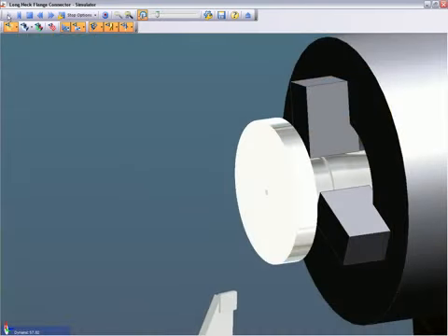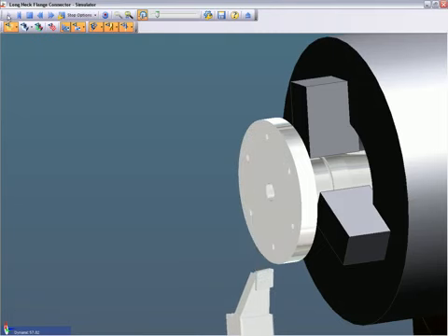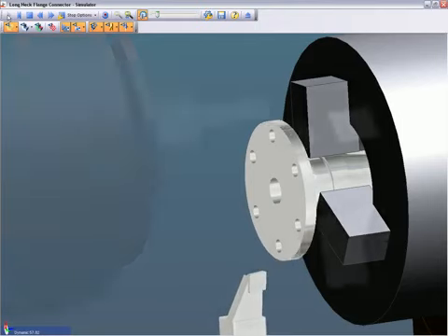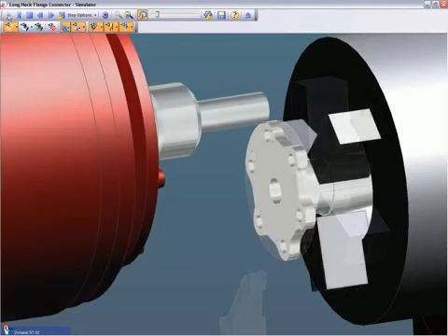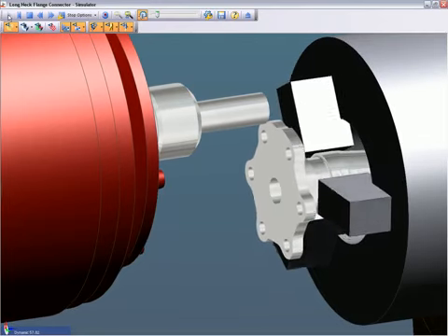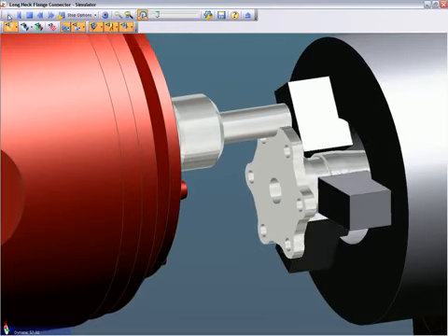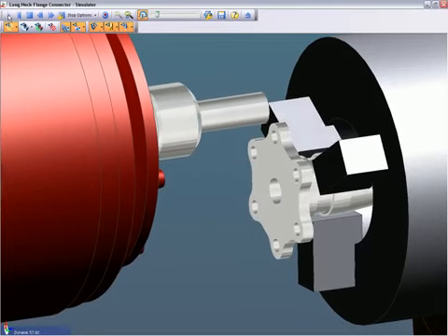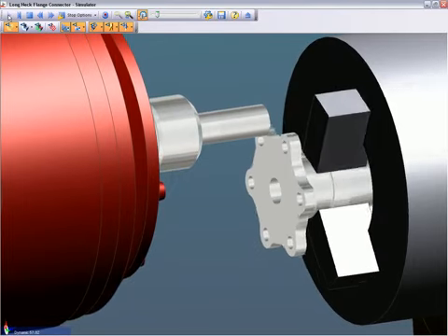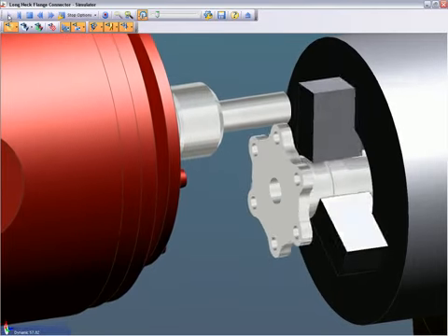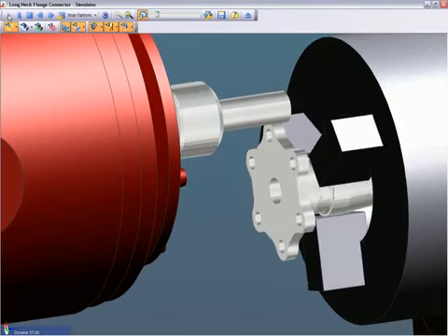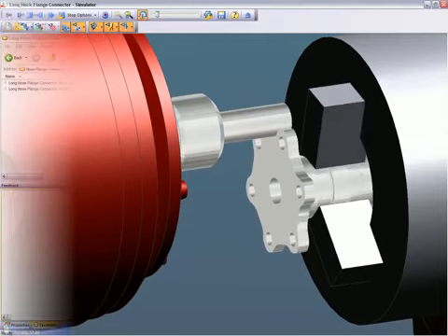Strategy Manager works on the information from the design intent of the 3D solid model. The solid model features have detailed information which will drive tool selection, approach values, cycle types, and the specific cycle parameters. The features are intelligent and pass information to the strategy which creates the machining cycle. For example, when running a face turn strategy, Edgecam references the stock model to determine the Z face stock amount. Then a decision is made whether or not to face the part.